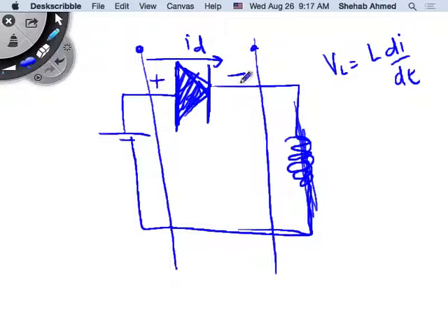So current would want to flow, because you have a low impedance here and you don't have a voltage opposing this voltage, right? And this node is higher in voltage than this node, so this is a good condition for this diode to conduct, correct? So this diode conducts. How about if I add a voltage here that is higher than this voltage? It will not conduct.